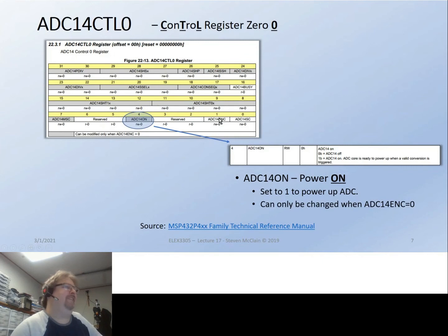Is it actually critical, the order that you write these in on the register, or no? Because it's all at once. Well, typically with the exception of the clutch, it'd be all at once. So usually I put the clutch in as a separate instruction, and I give it a few extra clock cycles to actually kick in. And then you can basically load the registers any way you want, as fast as you want, all at once, whatever.